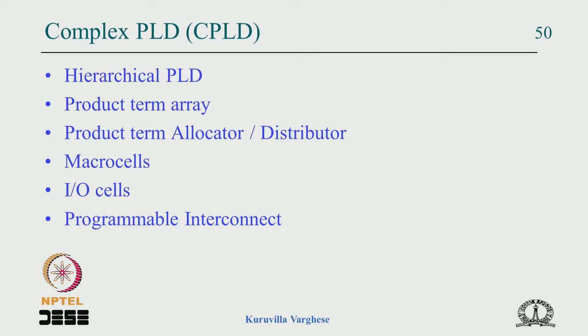At the power on you can bring all the flip flops to some required state, but if an FSM needs to control a particular reset, then you need to have the product term as reset, and that is done by the product term reset, which is what this allocator does. This allocator allocates a product term not only for AND gates and OR gates and XOR gates, but even to the control inputs of the flip flop. Okay. So let us come back to the slide.